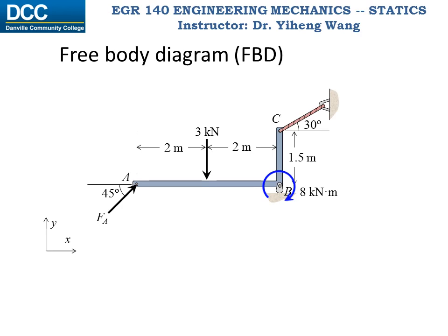Then, let's look at the rocker at point B. It allows motion along the horizontal direction. It allows rotations as well. It even allows the member to move upwards. The only motion it does not allow is for the member to move down. It exerts a force vertical upward.